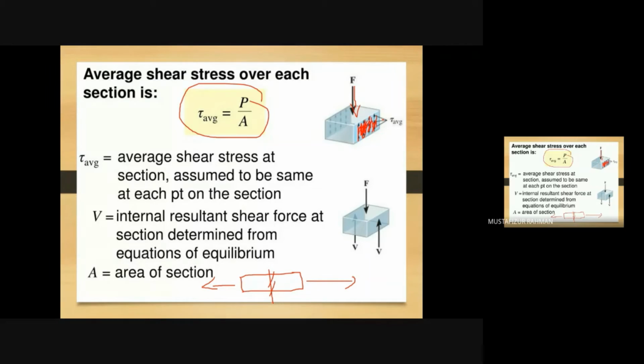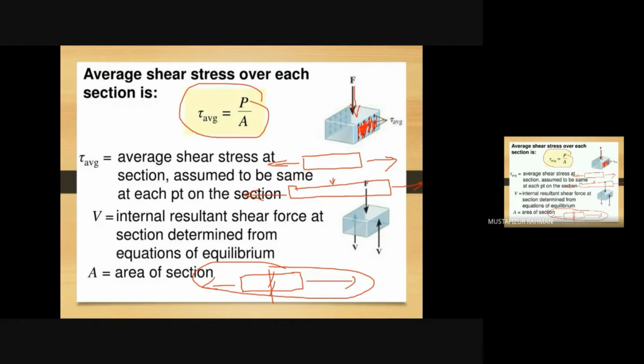Now, when we are talking about a direct stress, what may happen after some time? We are applying load, the force F is constant. After some time, the material is elongated. There is some strain in the material. If it is elongated, this cross section will reduce. Say, for example, there is 100 kilonewton force. Initially, the cross-sectional area was 10 centimeters square.